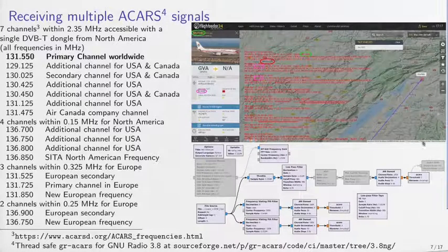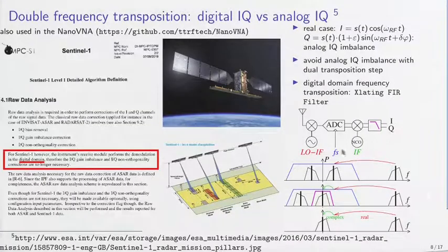So we've just seen that we can use this architecture where we have a coarse frequency transposition by the hardware, local oscillator sampling by the A to D converter on the bandwidth of the sampling frequency, and a second transposition to bring any information we might be interested in centered on 0 hertz. But can we use this information differently?